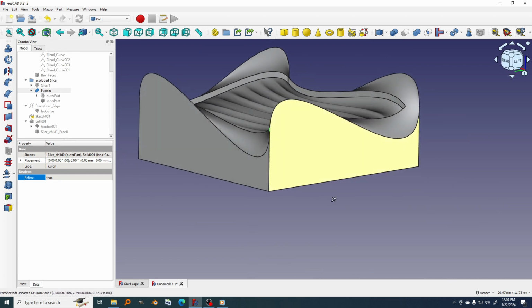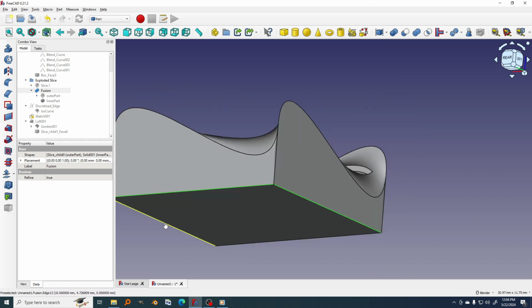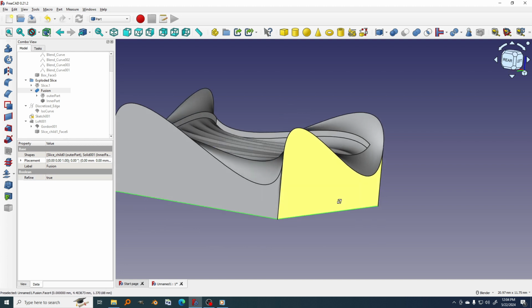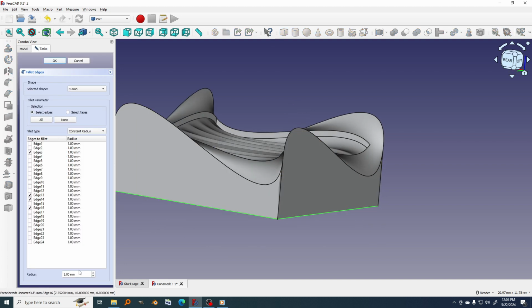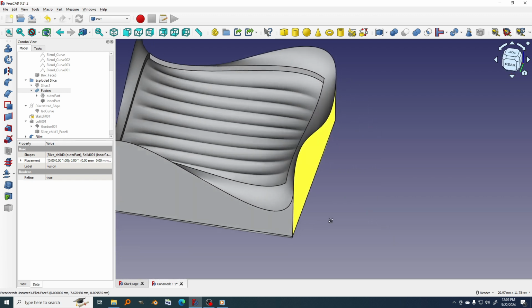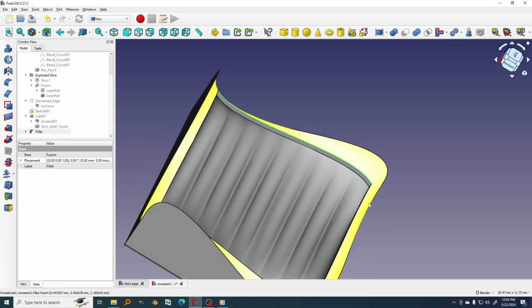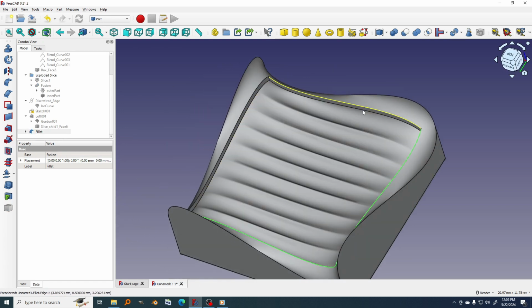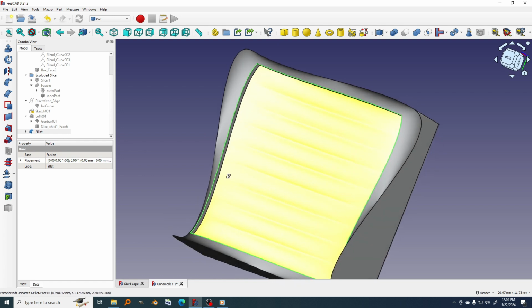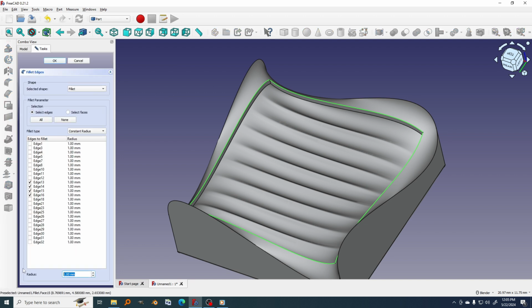Let's try to fillet this edge. So I select this edge, these 4 edges down below, and fillet it. Let's try 0.2. Okay. Now you can see it's very clean, and we should also fillet this guy up here. Okay, let's try to fillet it. 0.1. Click OK.